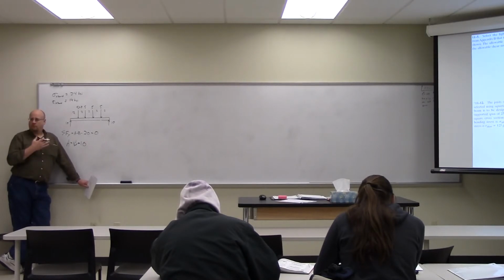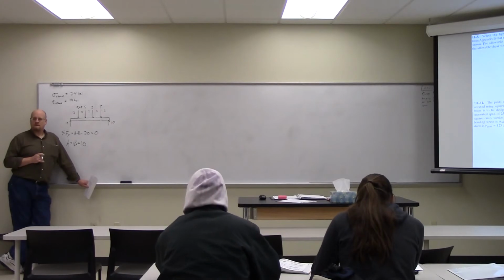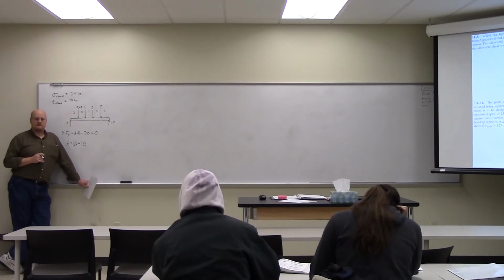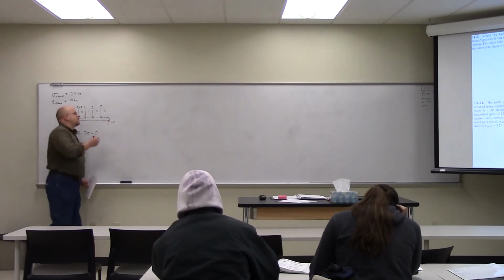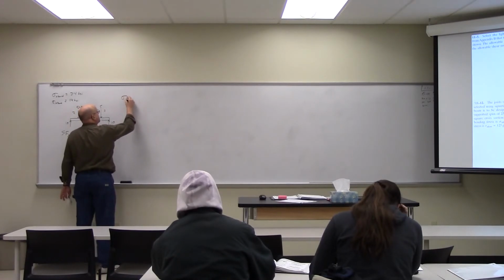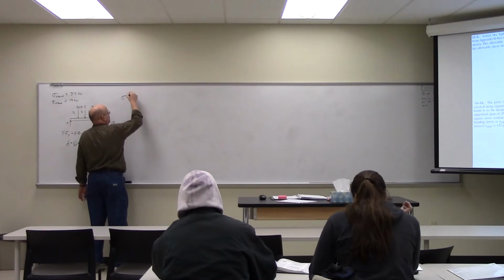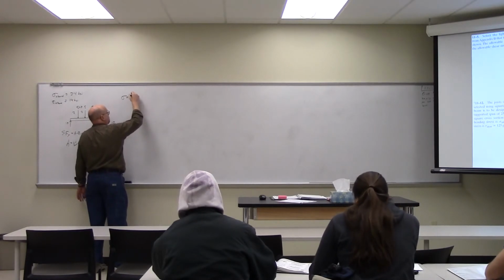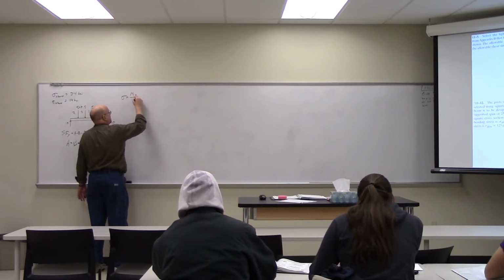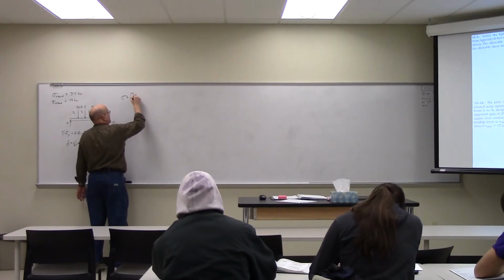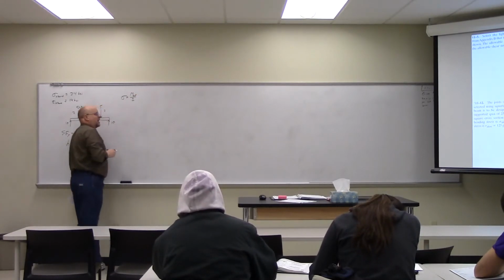Okay? So we're going to find sigma. So what do we need to find sigma? The maximum moment. Right, what's the equation we're going to use? My over I. And so we're going to find M max, the maximum moment.